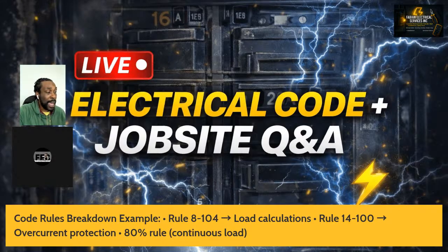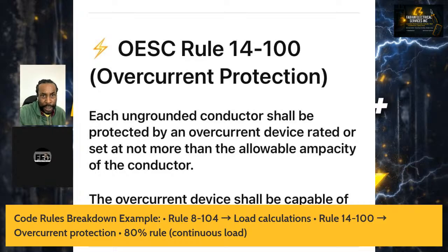So I'm going to go over to Rule 14-100, where it talks about the actual overcurrent protection. So OESC Rule 14-100, overcurrent protection: each ungrounded conductor shall be protected by an overcurrent device rated or set at not more than the allowable ampacity of the conductor.